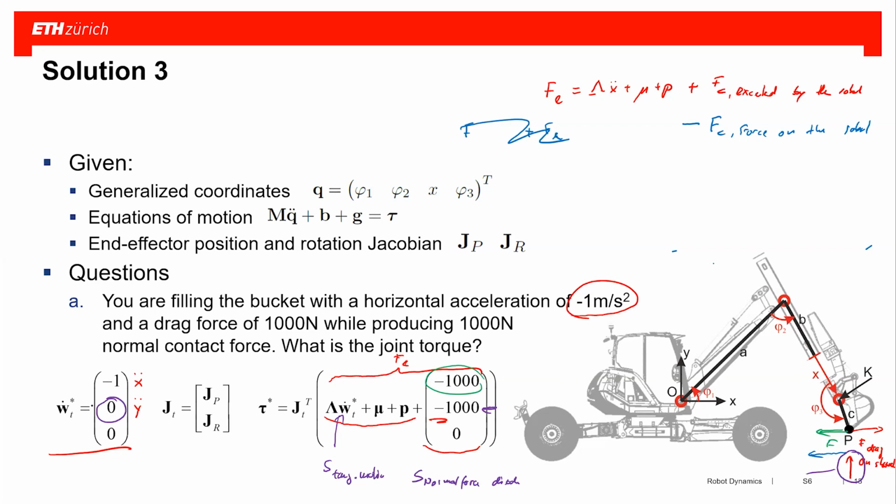It's a bit ugly for the drag part, because in the drag part we have both motion and we have force. So that means there you see both at the same time. You have to add this contact force also in the direction where you have motion, but you don't have the separation as we have seen it in the classical operational space control. But it's no problem, so the formula is still correct.